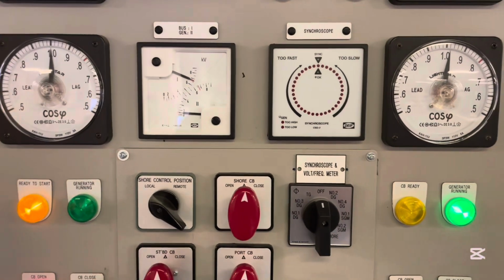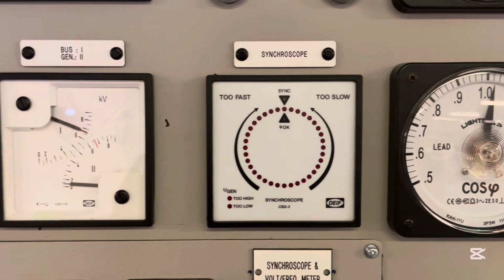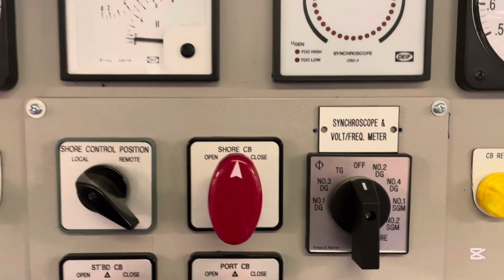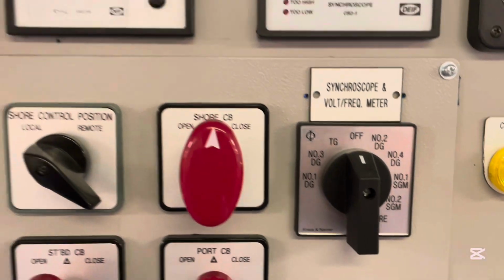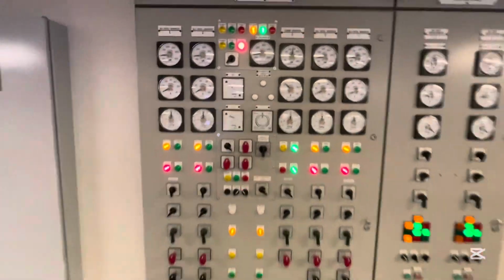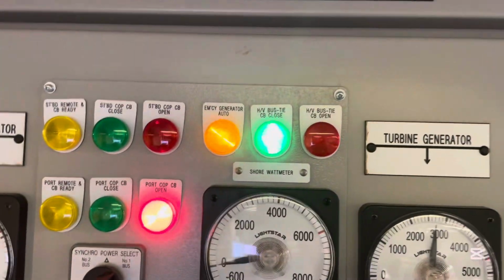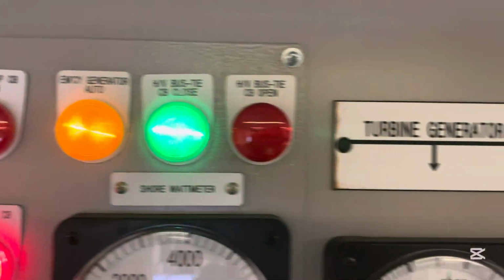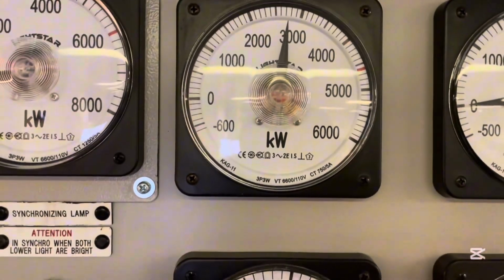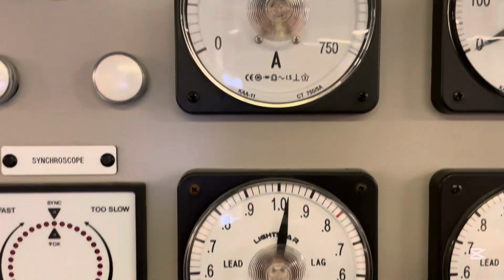Just to give you a refresh, this is a synchroscope, which is in the control panel. This is also part of the auxiliary engine control system. Basically, if you want to parallel 2 generators, we know that voltage, phase sequence, and frequency have to match each other. So we use the synchroscope, so that the incoming generator can be taken on load or made to run in parallel with the already running generator.